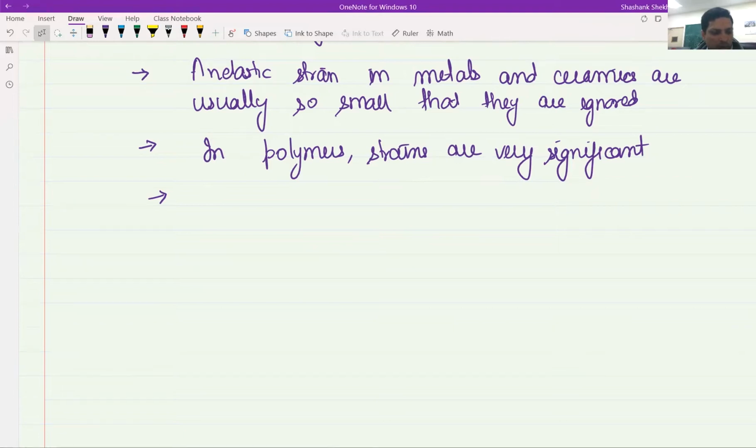So for example, you may see sagging of wooden beams, denting of vinyl floors, and loss of dimensional stability in some of the components. And these are all examples of viscoelastic deformation, which is undesirable. And as I mentioned in the example, this does not happen only in the polymers. It sometimes also happens in non-polymers, and it is undesirable over there too. But this is one of the primary reasons why polymers are still not used as a structural material, because this problem of viscoelasticity is what makes them undesirable.